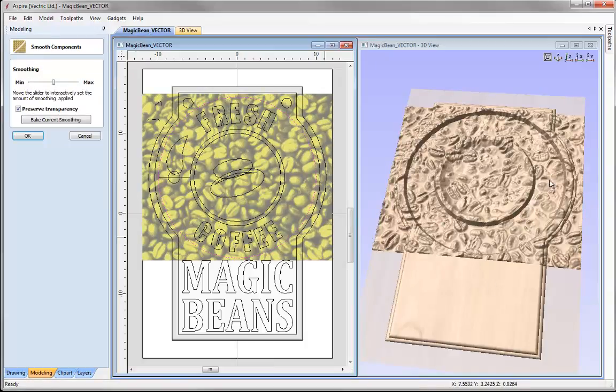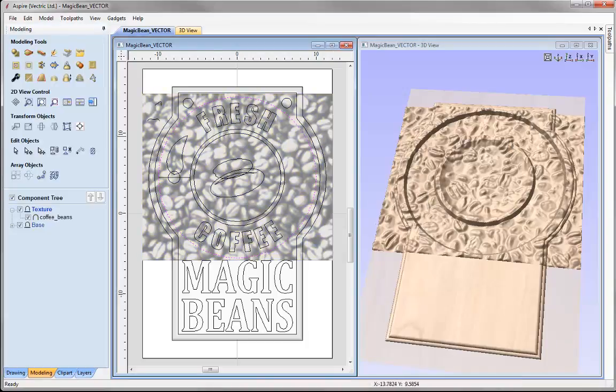It's just going to do that at default of 50%. We can see already it's smoothed that down a lot. Let's just maximise that, see how that looks. Okay, so we've really smoothed that off and reduced the noise. So I'm okay with that. So we'll just OK that and start thinking about how to crop that down to that recess shape there.